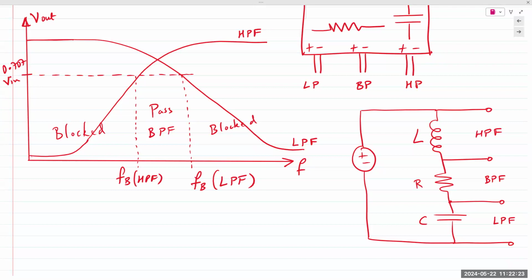One of them would go to a tweeter, one to a mid-range, another one to your woofer. And then frequencies below the woofer are reproduced by a specialized device known as a subwoofer. The lower you go in frequencies, the more power you need. So if you want good sound reproduction, you need an amplifier which can supply a whole lot of power.